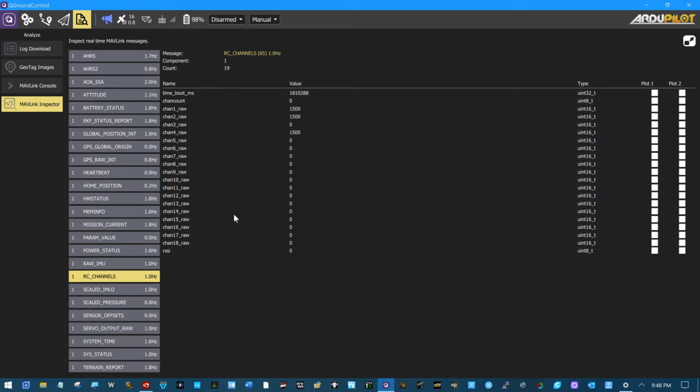I was telling somebody last night to go into their telemetry logs and look at their ESC, which might be channel 3 on an airplane, and when they were switching into auto mode, which I can overlay those two in Mission Planner and know exactly when you switched into auto mode, and it will show you exactly what the output of RC channel 3 did at that instance.